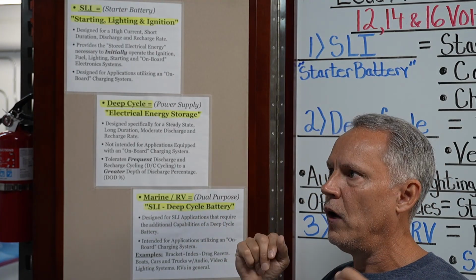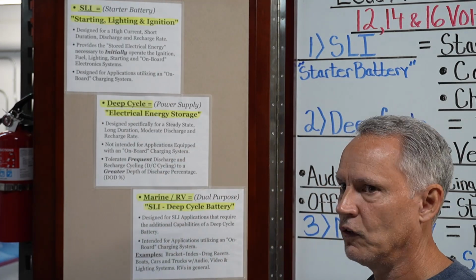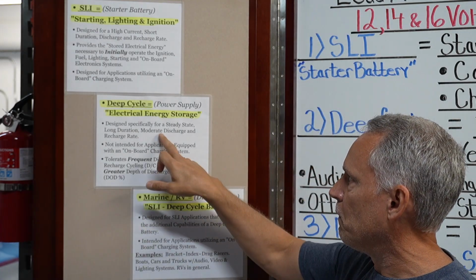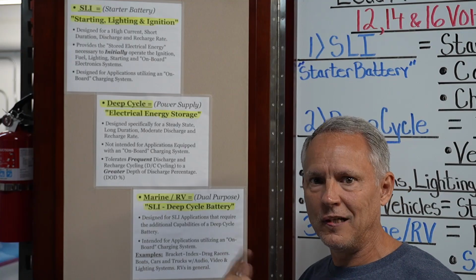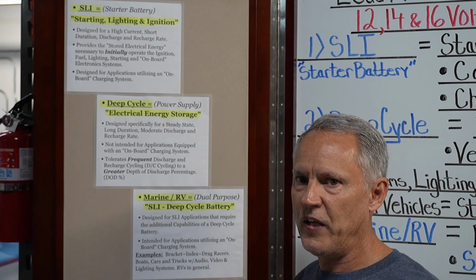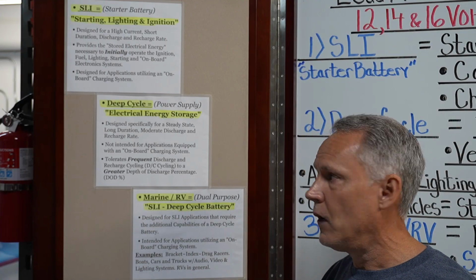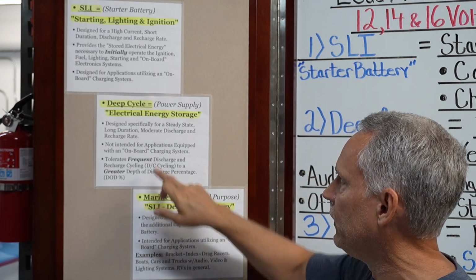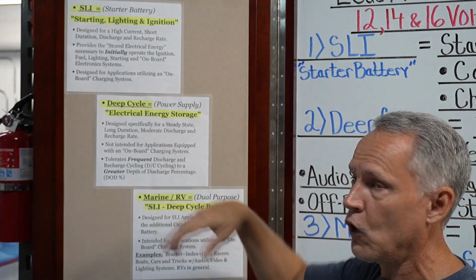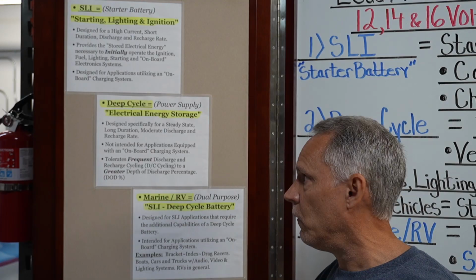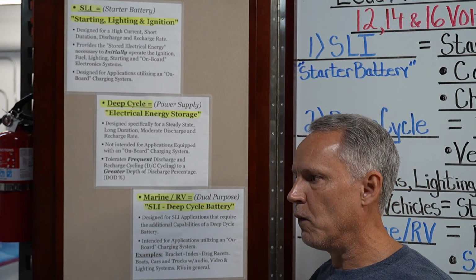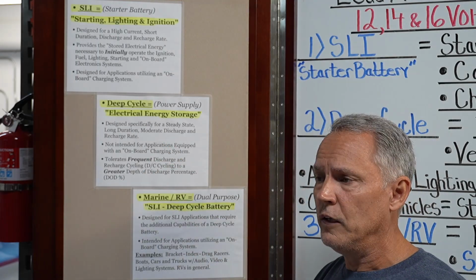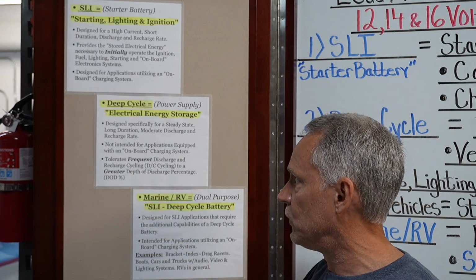and rate. So for example, let's say that to start the vehicle, it's a 250 amp draw on the battery. Well, a deep cycle battery, for example, let's say you're powering up some accessories in a vehicle and that's 15 amps or 20 amps, much less, but it'll do it for a very long time. And it's then designed to be recharged, and in this case, since there is no onboard charging system on the vehicle, it's externally recharged through a battery charger of some sort. And it's done at a moderate rate. So it has a moderate discharge and a moderate recharge rate.